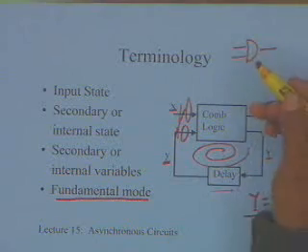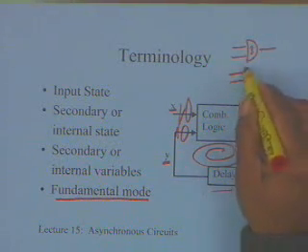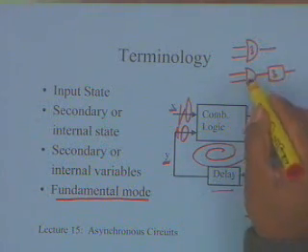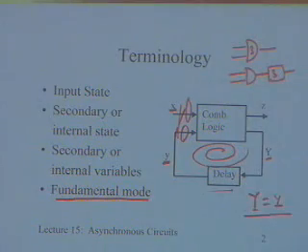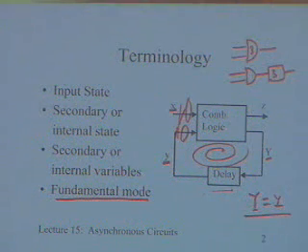This particular gate also has some delay, let us say a 3 nanosecond delay. I can break it down into an ideal AND gate which has 0 delay, followed by a 3 nanosecond delay. So this is a very notional breakdown. I do not have to design anything.